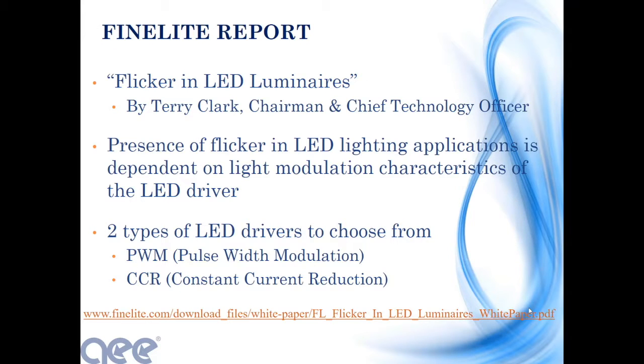Now, flicker in LED luminaires is an important consideration. There was a report written by Terry Clark, the chairman and chief technology officer of Fine Light, and he wrote this paper a couple years ago, Flicker in LED luminaires. The presence of flicker in LED lighting applications is dependent on the light modulation characteristics of the LED driver. There's two types of LED drivers to choose from: pulse width modulation and constant current reduction. You're going to hear that several times today.